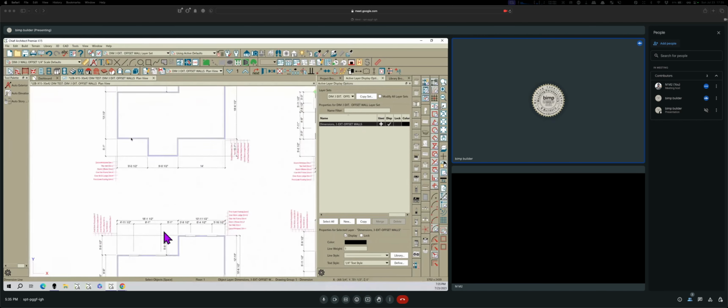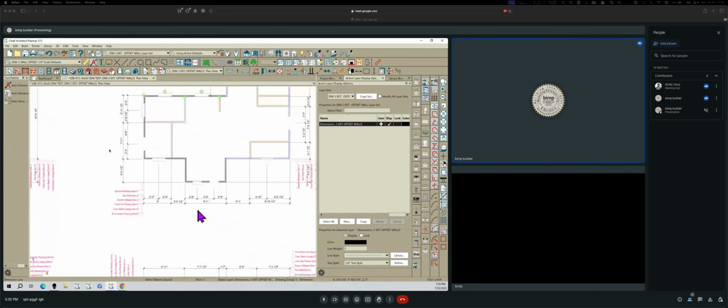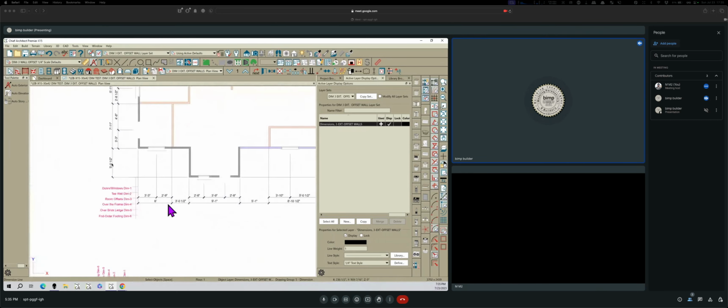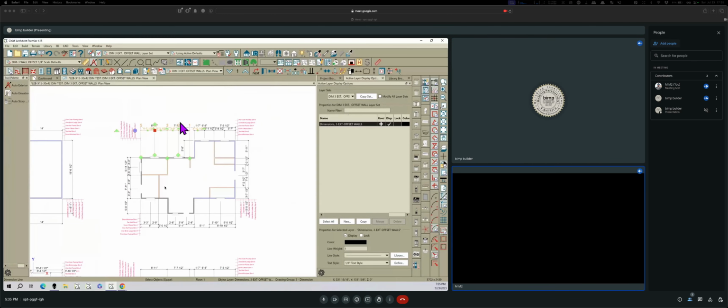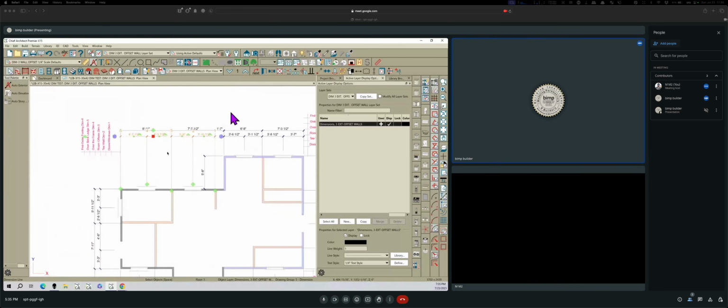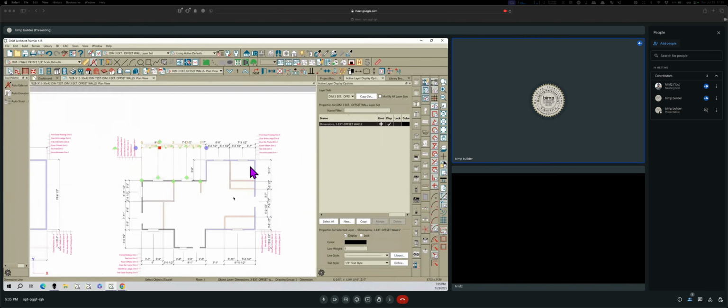What I like is on some of the plans you've done where you have a framing plan, and I only need to know exterior walls and openings and tees, so I can just lay that out. I can do all my outside walls that way, and then when I've got my outside walls done, I'll do a couple inside if I need to, like to brace the wall so the outside wall doesn't tip over, and those are easy.